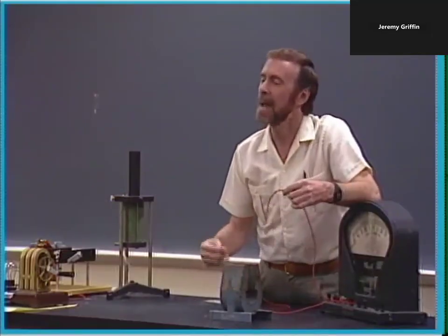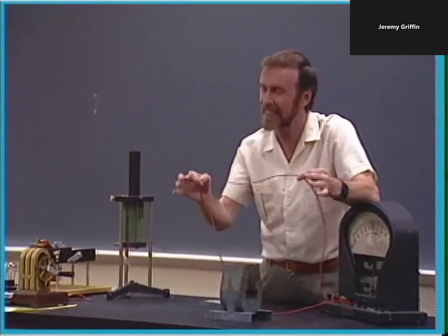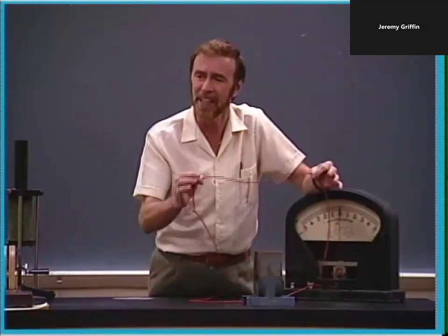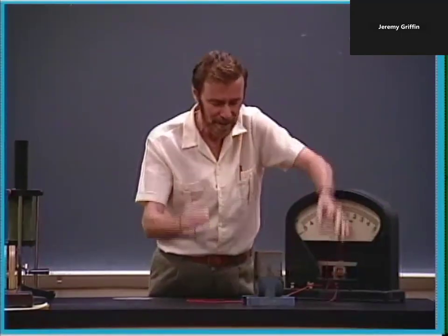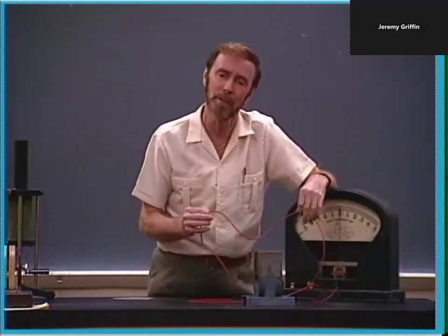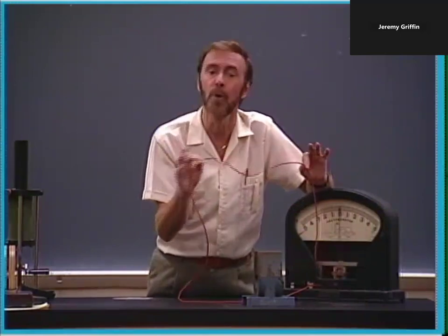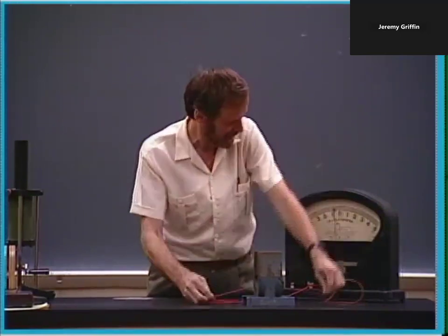And what it says is this, a little more complex. Change the magnetic field in a closed conducting loop of wire, doesn't even have to be conducting. Just change the magnetic field intensity in a closed loop, and you will induce a voltage in that loop. Now, this loop happens to be a copper wire, so the voltage in that produces a current. So look at this, you get a current.